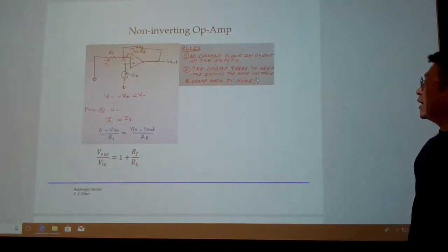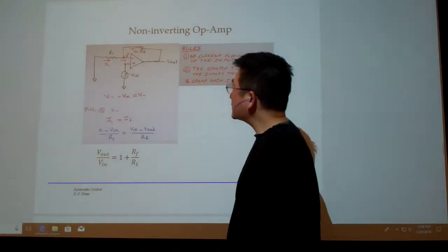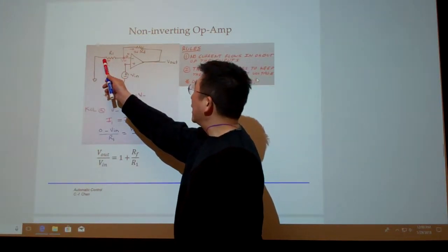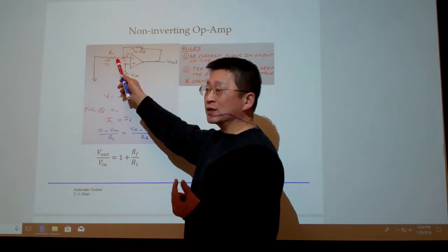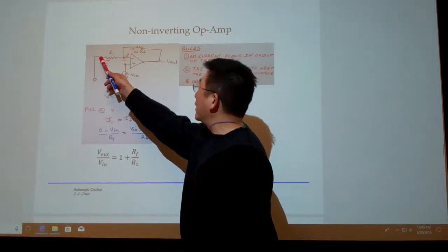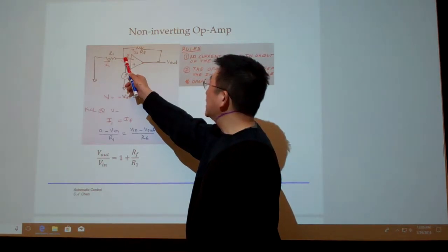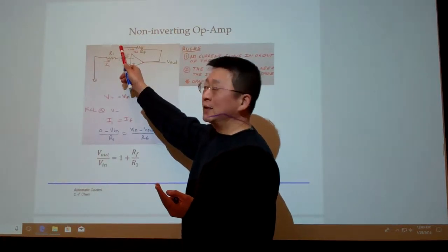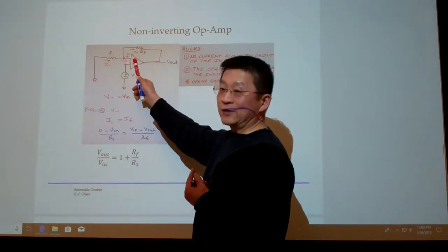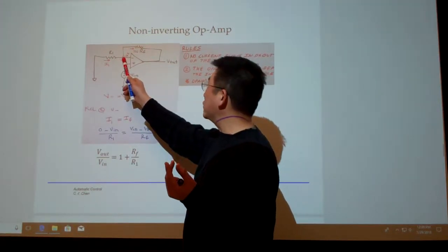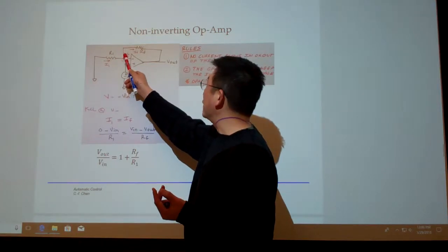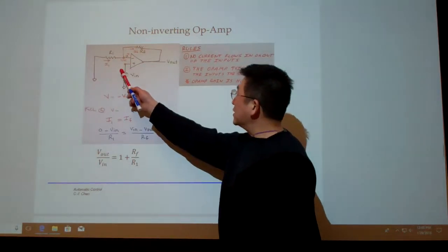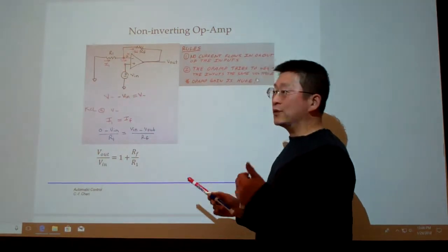The first rule is no current flowing. So assuming right now, through these resistors there's a current we call I1. I1 comes through here to this point, and the electrons have two options, going here and going here. But we're assuming there's no current coming in, right? So basically, all of the electrons will go this path, and the current flow will go in this way. So that's the first rule. And that means in terms of symbols, I1 equals IF, so we apply the first rule.